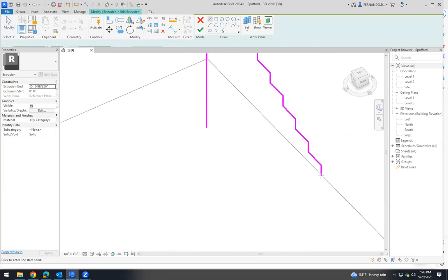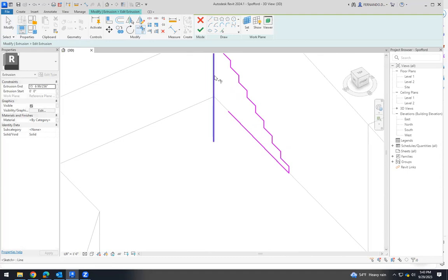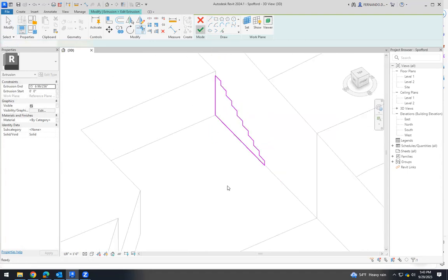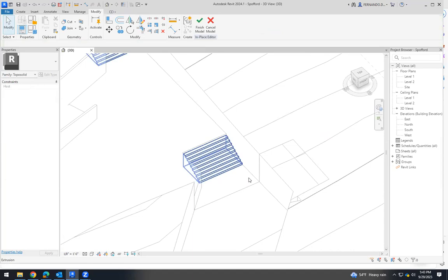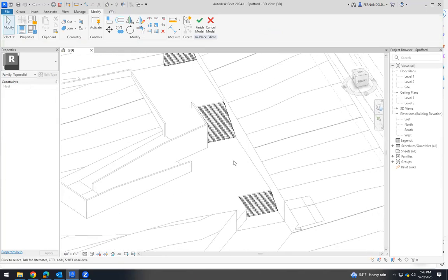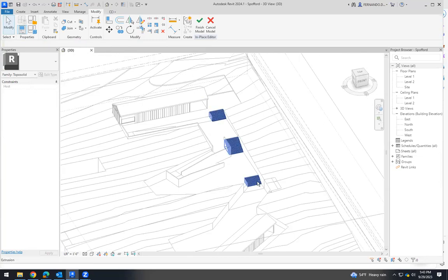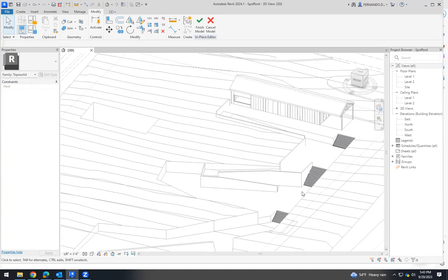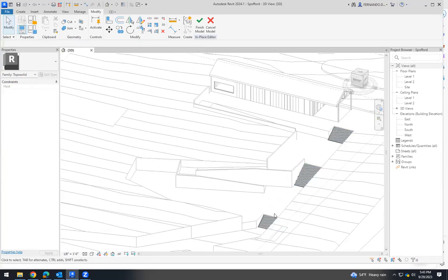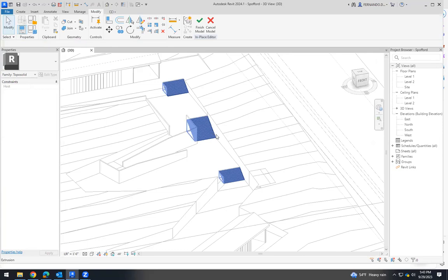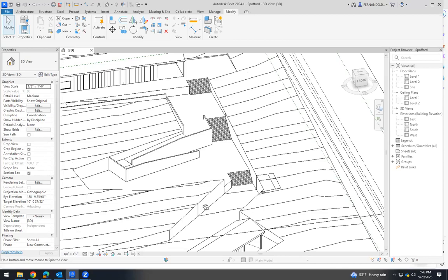And I can go all this way and do this. Okay, so that's the easiest way because all the stairs are lined up to this wall and I don't have to create steps from scratch every time I do this. If we make sure that this line is a straight line, we can do that easily because we created first the first reference plane. So if I don't change this reference plane, that will work.